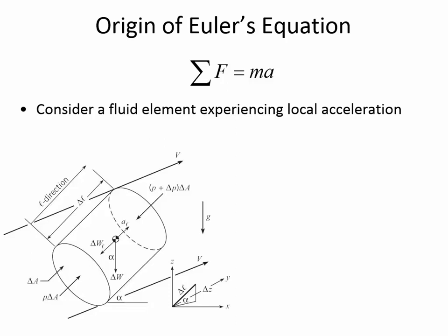L happens to be the direction that this fluid is accelerating in. If we measure some distance between one part of the liquid and another part, then the pressure is going to change. Here on this face, they're saying the pressure is P plus delta P. And then on this face, the pressure multiplied by the area tells us the force that's acting on the fluid.